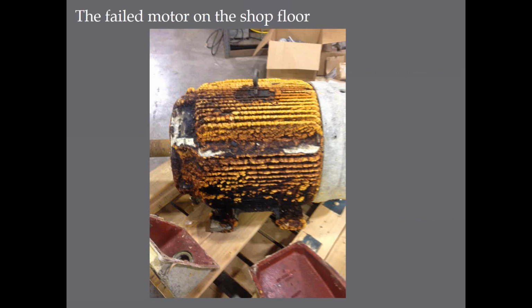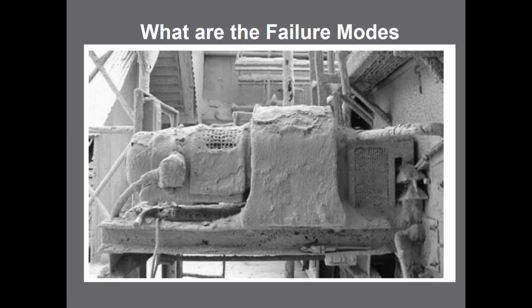So we can't have these kind of things in our plants. What's the PM task? Were we checking this motor every week or every month? What was the frequency? What were we looking for? Was it looking for hot bearings? But again, the PM task here, clean the motor. This was at a cement plant. Everything completely covered. PM task was done the day before. I'm not sure what they checked on it.